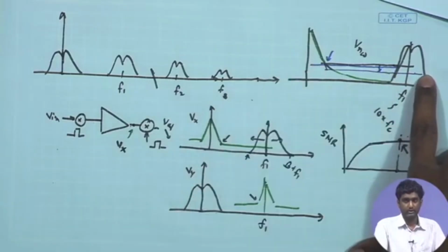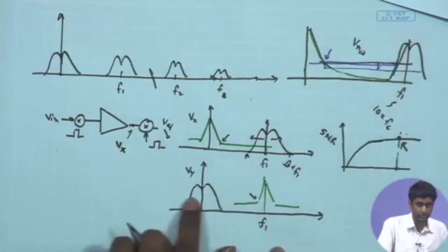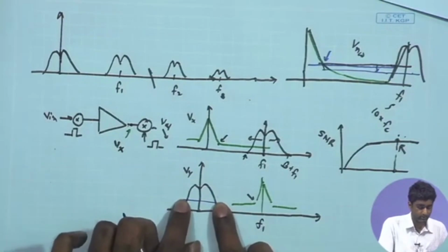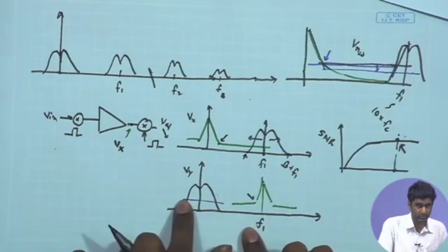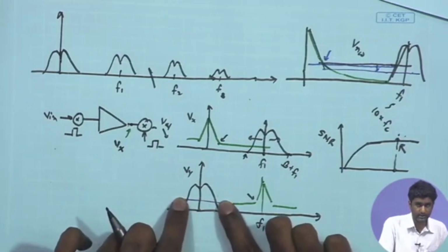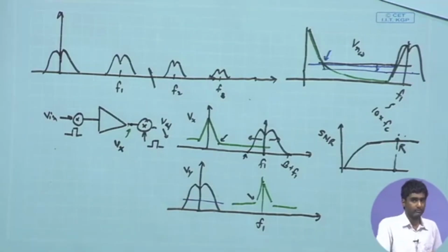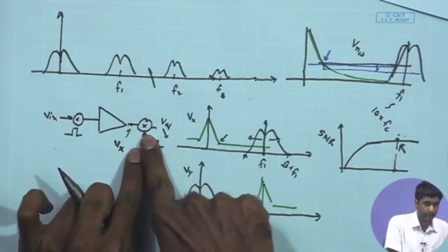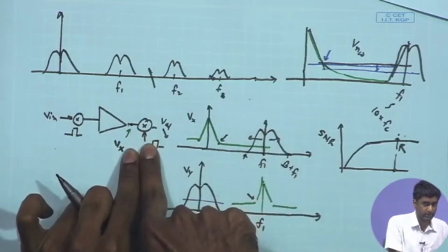is lower. For example, after the anti-chopping operation, when you are pushing the signal back at this frequency, there once again the 1/f noise is not coming into picture, but the white noise indeed is coming into picture, and that is once again aligned with your signal content. Not only this, if you see after the anti-chopping process, you also have the higher harmonics of this clock signal coming at this point, right.